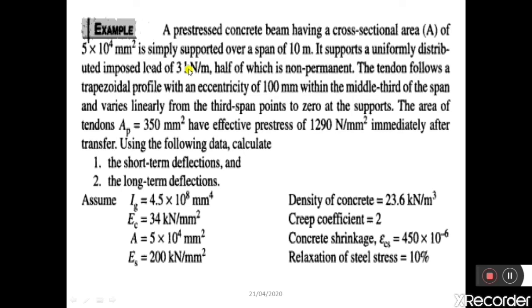When the students leave the classroom, that live load, that movable load in the form of benches and desks, will act as a dead load, because throughout the year those benches and desks will be within that classroom only. Hence it is similar to that one.